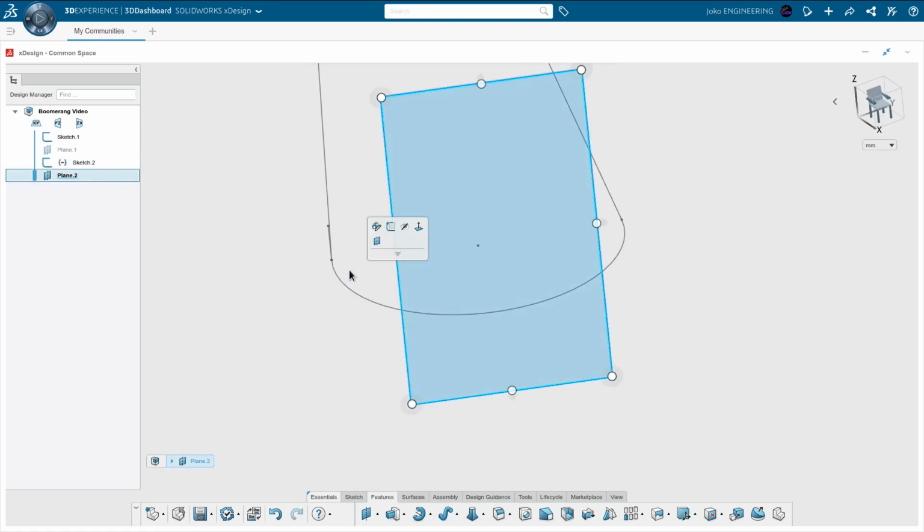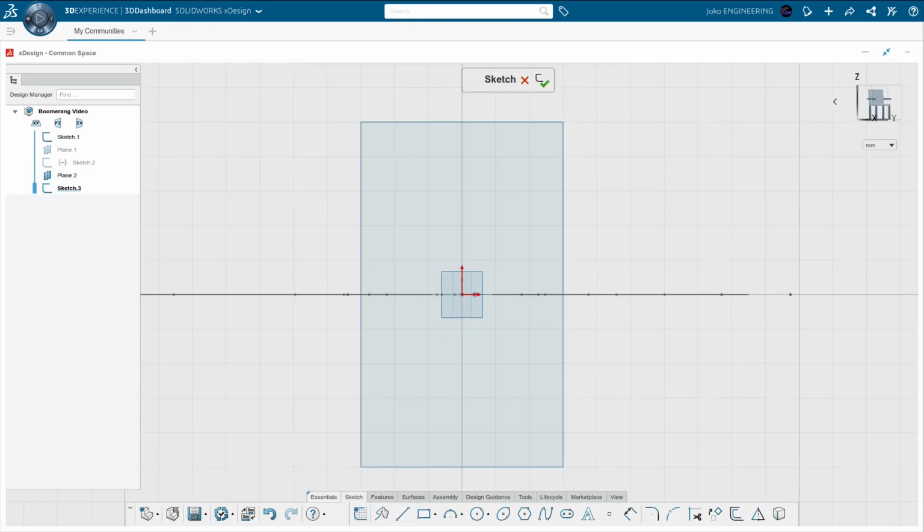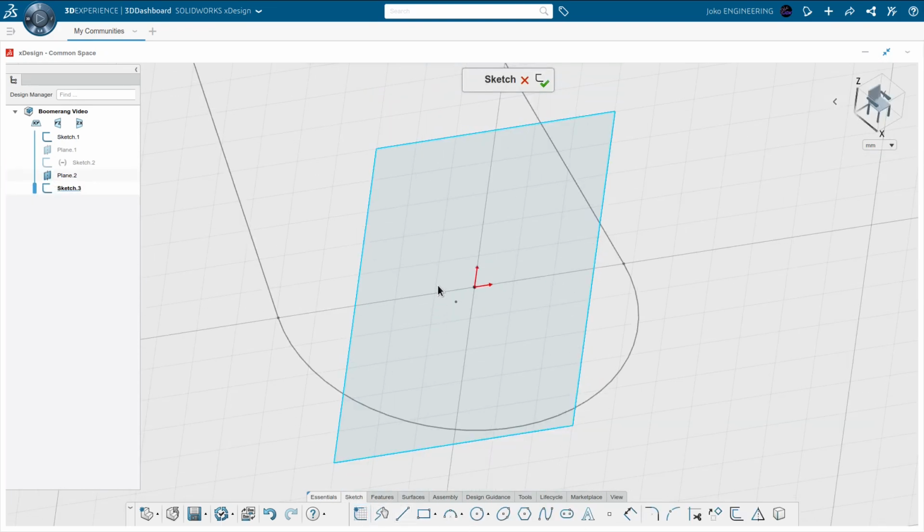And then I can make kind of an arrow or a foil profile sketch. So we're going to create a new sketch. You can see it's pretty simple, just like SolidWorks. And we're going to go with this arc dimension. We're going to go with 12. We're going to go with horizontal down here. Of course, I have to hold the Shift key, not the Control key. Onshape is the same way. I think when you're in a browser, the Control key has to be used for other stuff.